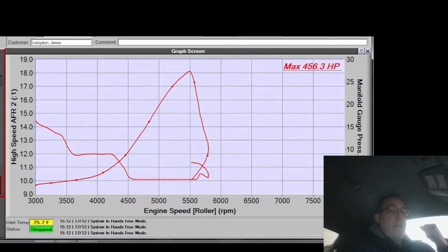You're going to tip in, air's going to come in. The fuel that's right at the saturation point, at the increase in pressure, is going to plate out into the puddle, and you're going to get less of it into your cylinder. Fuel that's well below the saturation point, when the pressure goes up, is not going to puddle as bad. But the stuff that's right at that saturation point, which is a good portion of it, a lot of it's going to go to the puddle or just become saturated large droplets, and large droplets don't atomize well and they don't burn well, which will make the car boggy as well. It'll make it lean, even though technically you could have too much fuel in the cylinder.